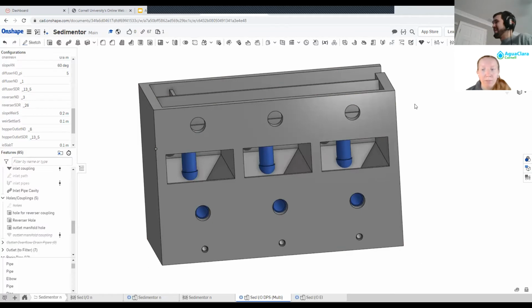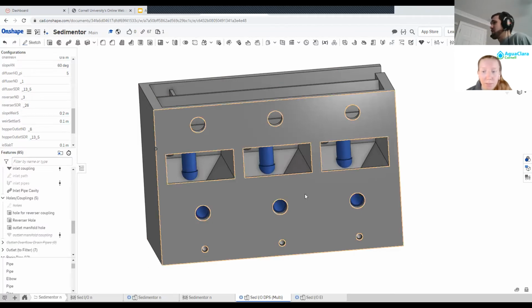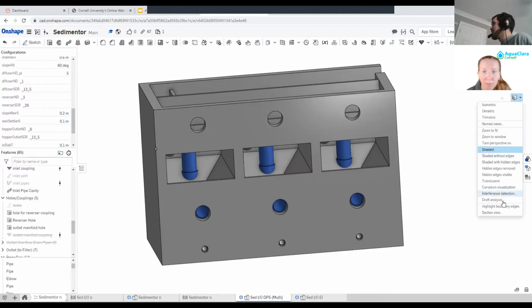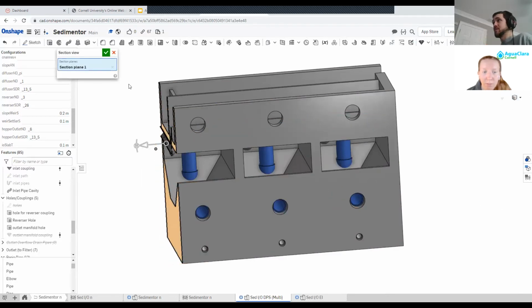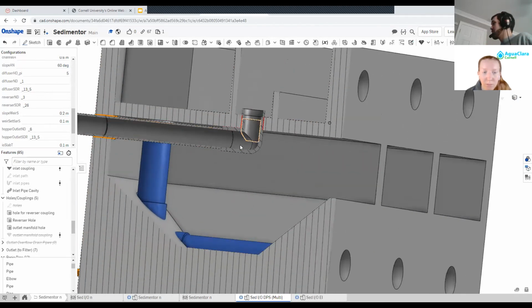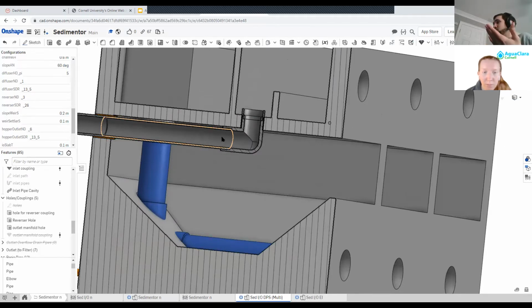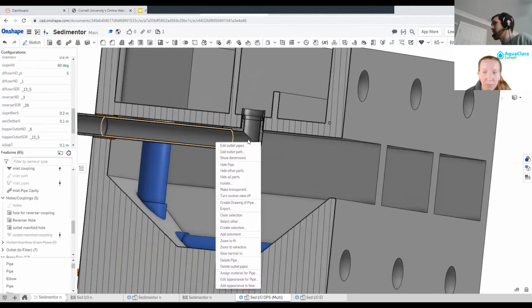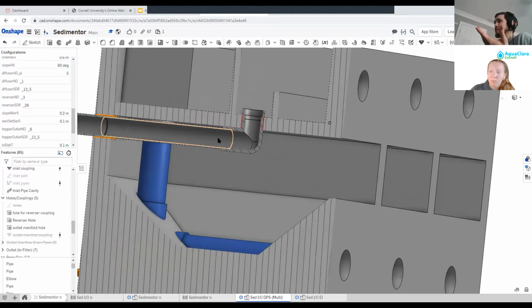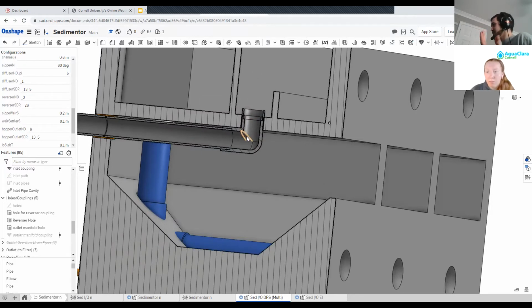The SED-IO manages the input and output flow to the SED tank from this front face. So naturally, it has a lot of pipes and fittings to carry this flow. And this gives us a good reason to use the Pipeline tool, which makes it far easier to create strings of pipes. So we can create this outlet pipe far more easily by simply selecting 2 lines plus a vertex in between, which will create 2 pipes plus an elbow to connect them.